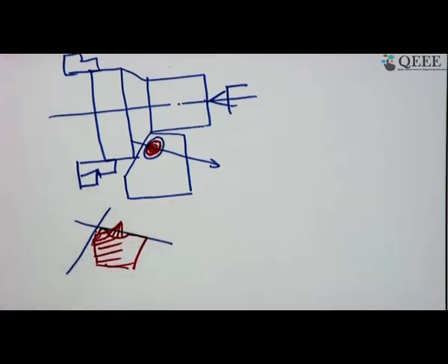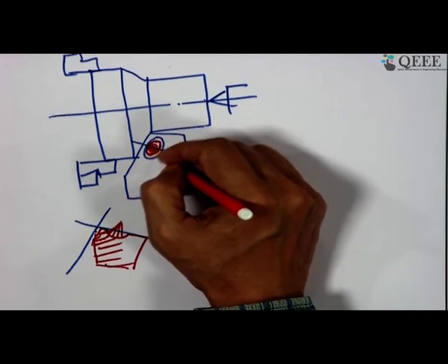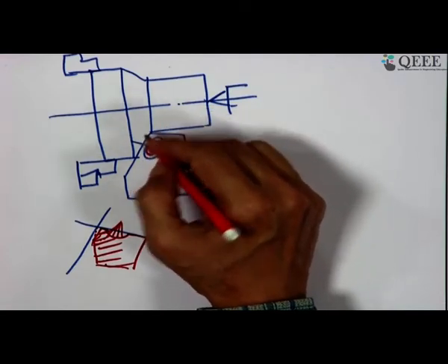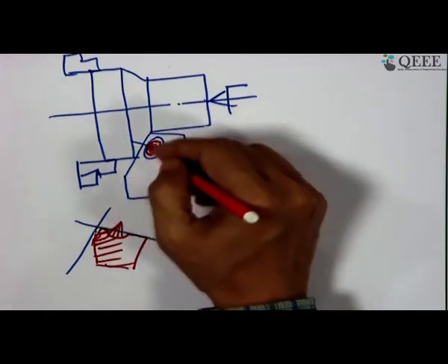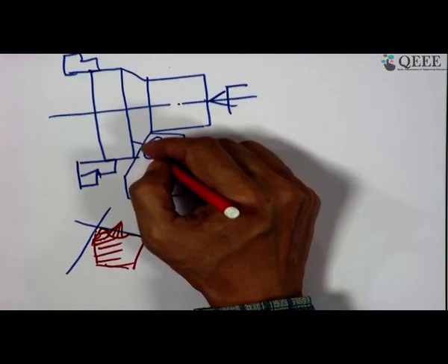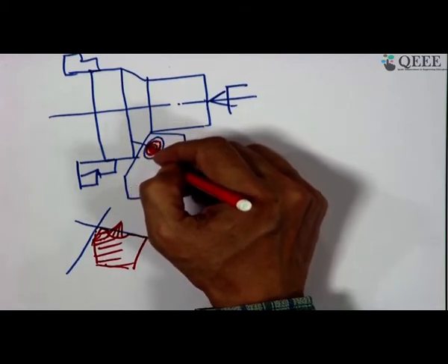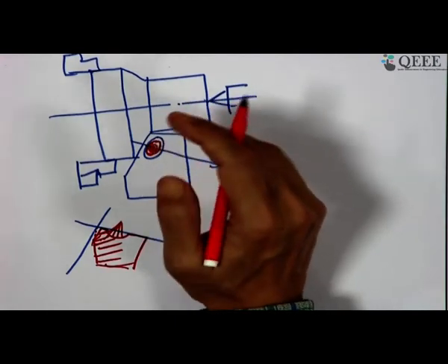So, friends, there also we have to be very careful about how far we can allow this crater to grow, in order not to promote catastrophic failure because of this thinning of the section and the land, the material available between the cutting edge and the leading edge of the crater. So, this is the point one has to look into.